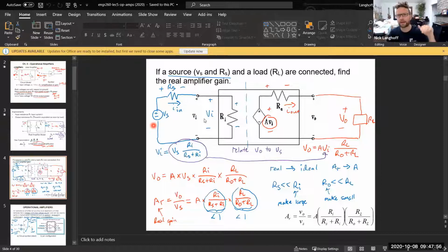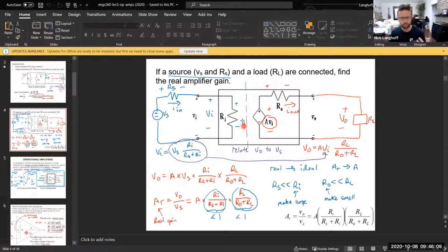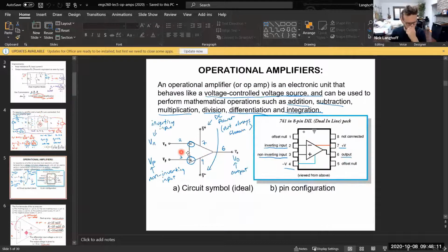So keep that in mind as you approach some of those problems in the op-amp homework on WebAssign. Then we introduced the operational amplifier, and the nice thing is it condenses this amplifier model down to a simple schematic symbol that's shown as a triangle. When you're working in the lab, these often show up as an 8-pin package, and the inputs are on certain pins.